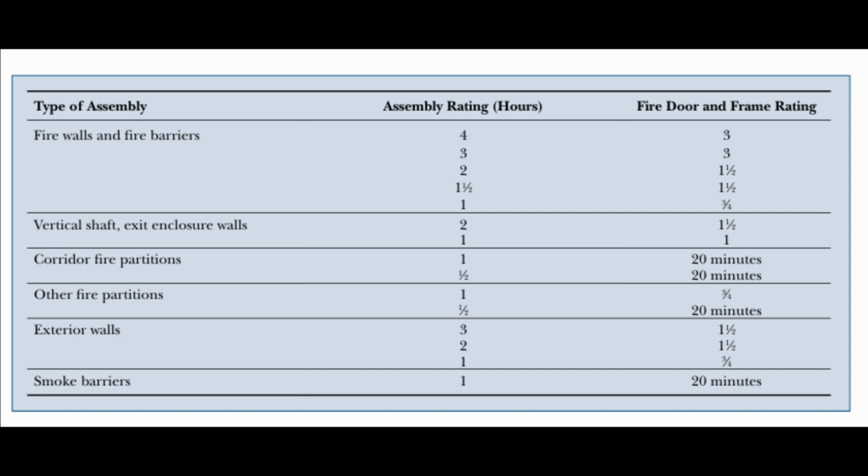These labels must not be painted over during construction so that the fire rating of the door can be verified during future building inspections. Glass used in fire doors must itself also be fire rated, and it will not break and fall out of the opening for a specific length of time when exposed to the heat of the fire.